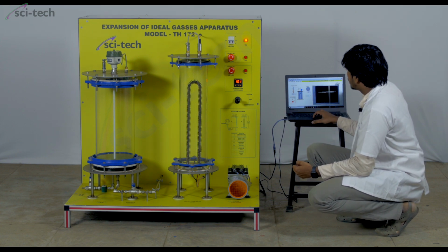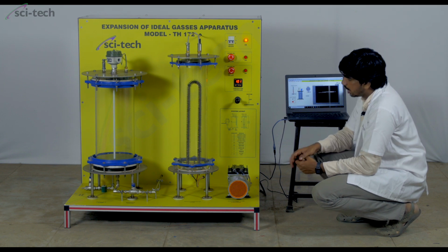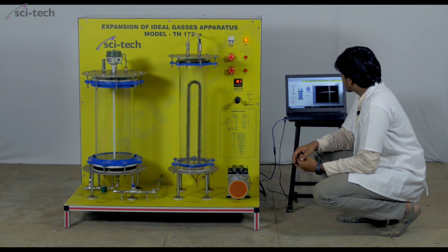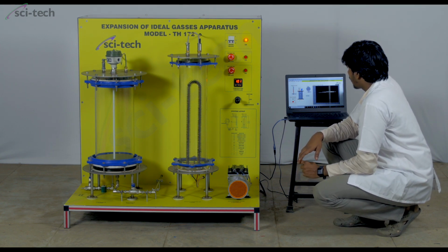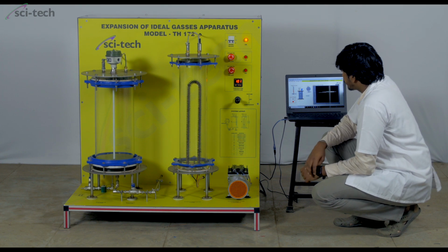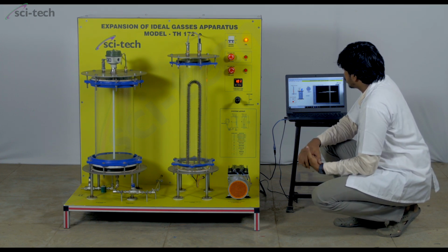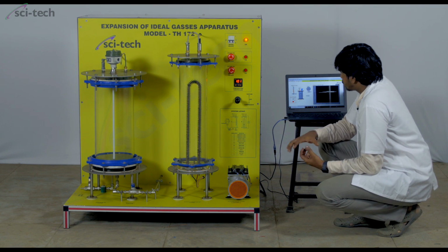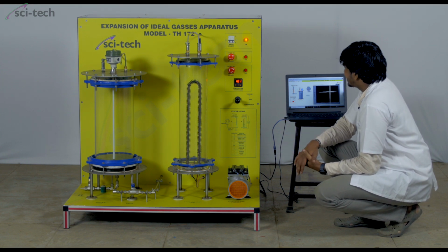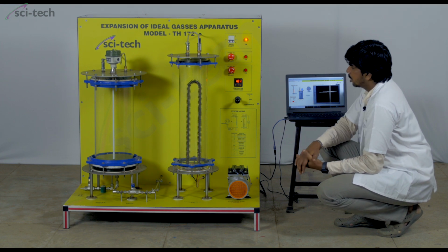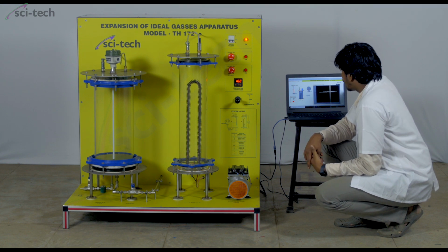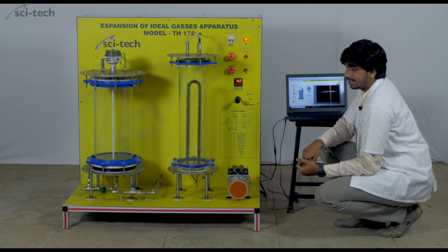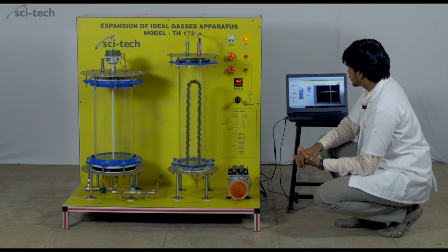I have already started the application. We have collected around 50 or 60 observations. Now the temperature has settled at around 108 degrees Celsius and the pressure is around 0.12 bar. Slowly the temperature will decrease because the heat output is 0 right now, as our heater is turned off. As you can see, now our temperature is 107 and the pressure is 0.1172 bar. So now the cooling has initiated.